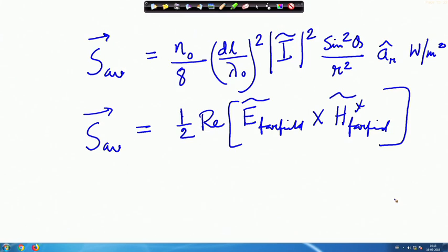Usually it is a plus j component of power, that is why they are called inductive fields, as if in an inductor there is a local storage of energy. That energy does not flow in a typical circuit also. So, here also near the antenna there is an energy storage, but that energy is not flowing. Only after a certain distance that energy starts flowing.